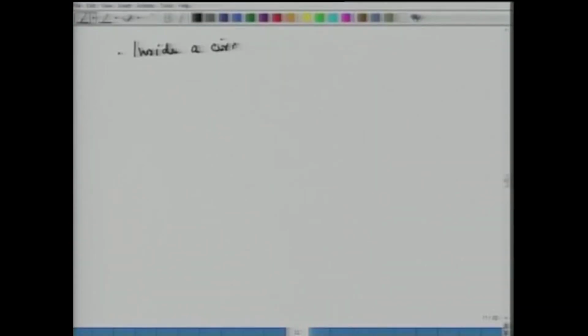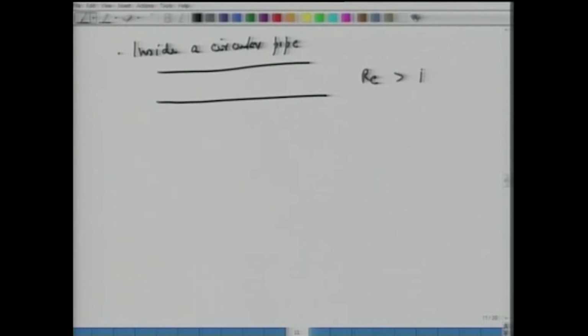It has been defined to make our calculation simpler in those cases where there are complexities in defining or solving the velocity profile. Similarly, we can take one more example, like flow inside a circular pipe. If the Reynolds number is very large, say 4000 and greater, then the velocity profile will not be parabolic and we have some flat velocity profile.